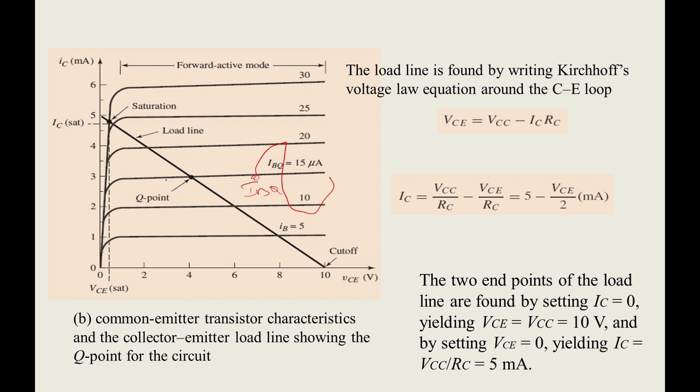So you can see here. How to find the maximum VCE voltage? You have the equation VCE equals VCC minus ICRC. To find the maximum VCE voltage, consider IC is 0. Then what is the formula? VCE equals VCC, you know already. What is the supply voltage? Supply voltage is 10. So keep the dot. So you got 1 point.